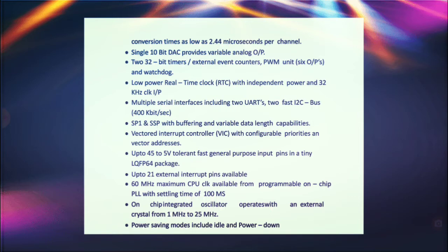Multiple serial interfaces including two UARTs, two fast I2C bus at 400 kilobits per second, SPI and SSP with buffering and variable data length capabilities. Vectored interrupt controller with configurable priorities and vector addresses.